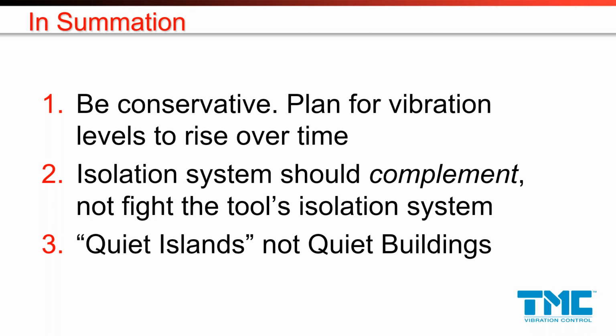So both actively isolated and rigid quiet islands could then be designed to match the tool footprint and the other requirements, and easily installed or moved around when needed. So I think, again, just in summation, best practice is a raised access floor, 18 or 24 inches, over a thick concrete slab.